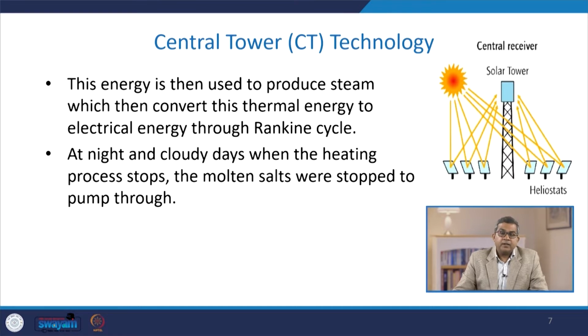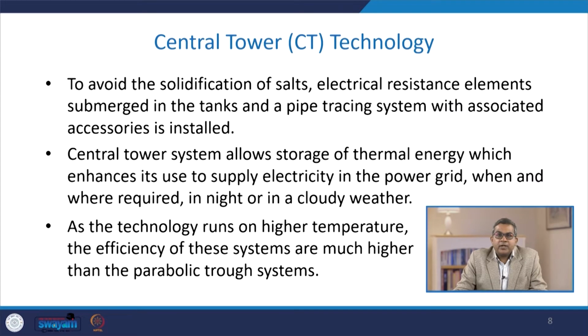Now at night and on cloudy days, when the heating process stops, the molten salt is no longer pumped through. To avoid the solidification of salt, electrical resistance elements may be submerged in the tank, and a pipe tracing system with associated accessories is installed.